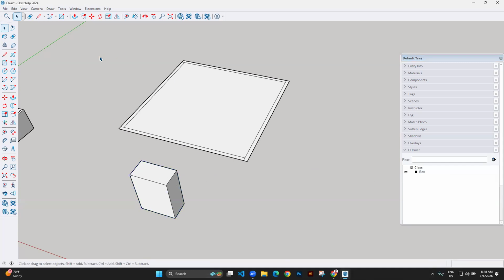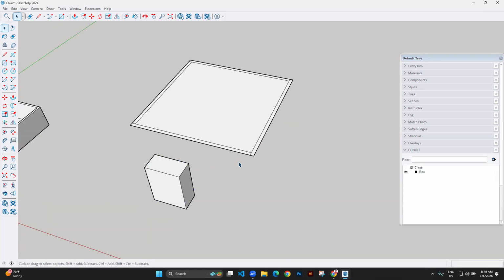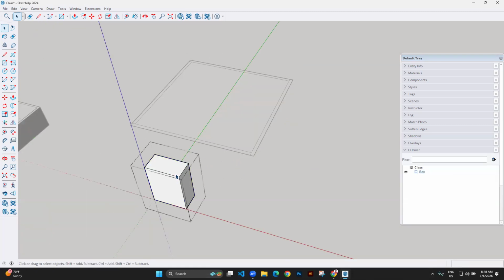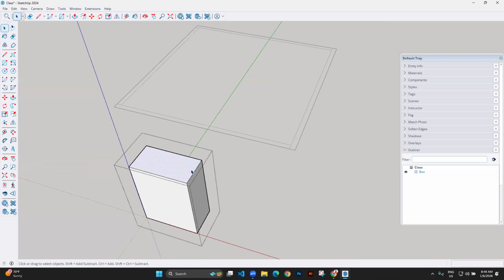Yeah, so this helps us, we can rename even this group and say this is a box. So that's how you group. You select what you want to group, then right click, select group. Now, how would you group here? The better approach is the moment you get a face, group it, then start editing. How do you edit a group? If I double click here, it opens that. A single click will select, but double click will open it. So this is the editing mode.